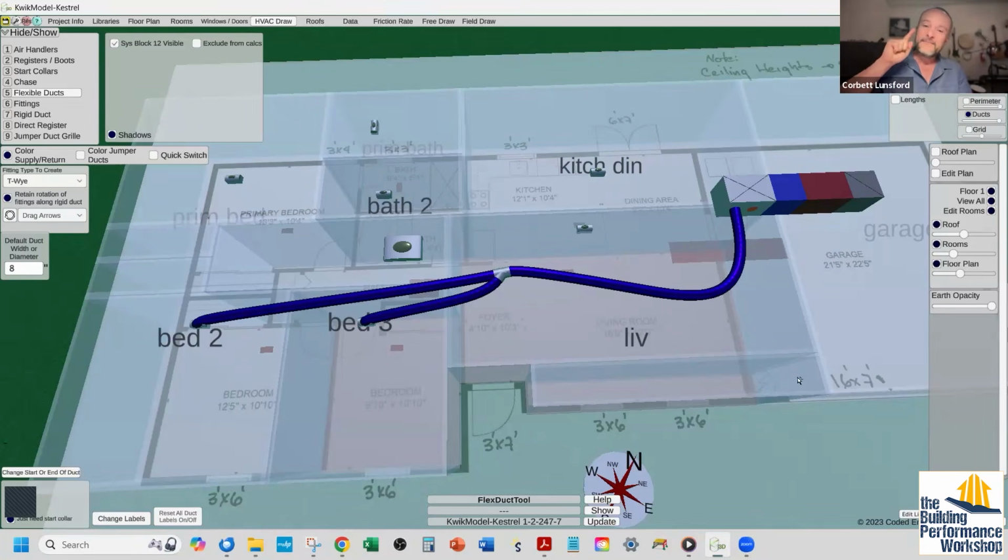But you did an experiment recently where you coiled up the flex duct. Everybody says you've got to install this stuff super straight, and you actually had an air handler, and then you did a whole 360 on the ducts. Several 360s, actually. And you had hardly any actual drop, a 15% reduction in airflow.